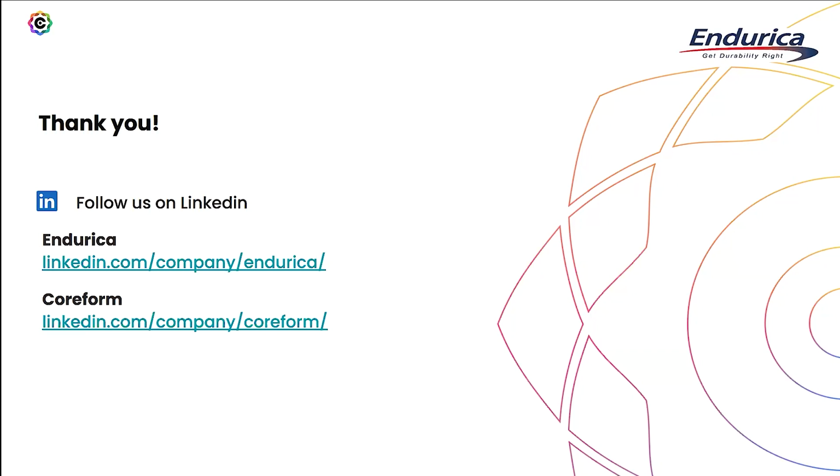But if there's a simulation you couldn't run because you couldn't get a mesh, well, then it's kind of useless. So, as engineers, we oftentimes have to make these modeling assumptions and defeaturing to be able to get a mesh that we can get a computation on, and then use good engineering judgment to interpret the results. And so that's another approach that you can take to handle this case of complex geometries.